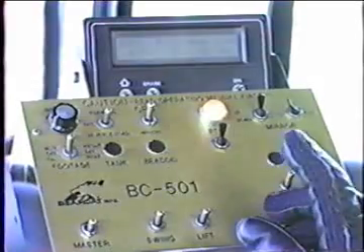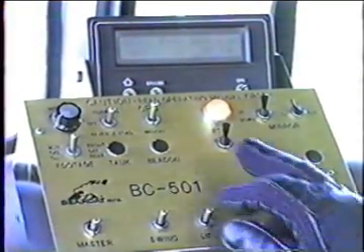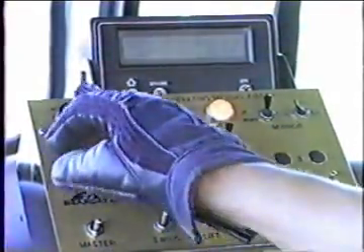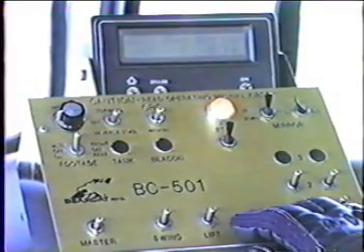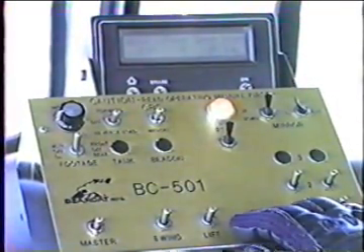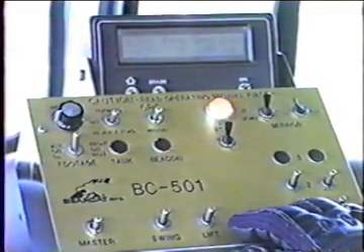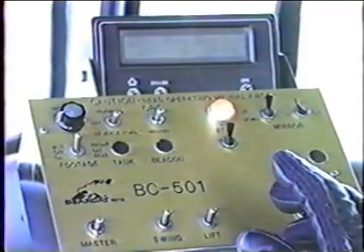As you back up to the tank trailer or to the transport, set your brake, move this to manual, put it in reverse load, and put it at full speed. Then go to the back of the truck, hook up the hose, open the trailer valve, and open the one valve on the back of the truck that we talked about when we were back there, and it's loading because the pump is running in reverse already when we get back there.